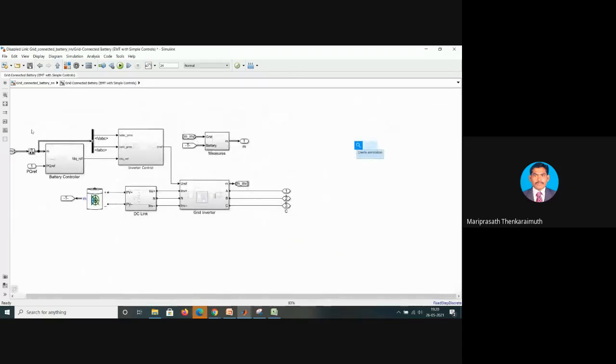It is the total setup to control the battery storing unit. The main part is the battery charging controller. The controller output is fed to the inverter control unit, and the inverter control unit controls the supply which is fed to the battery. An input capacitor DC link is there, which filters the DC supply fed to the battery.